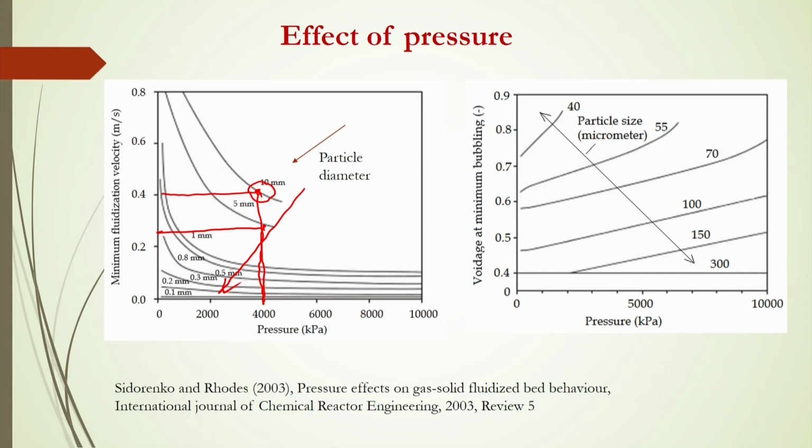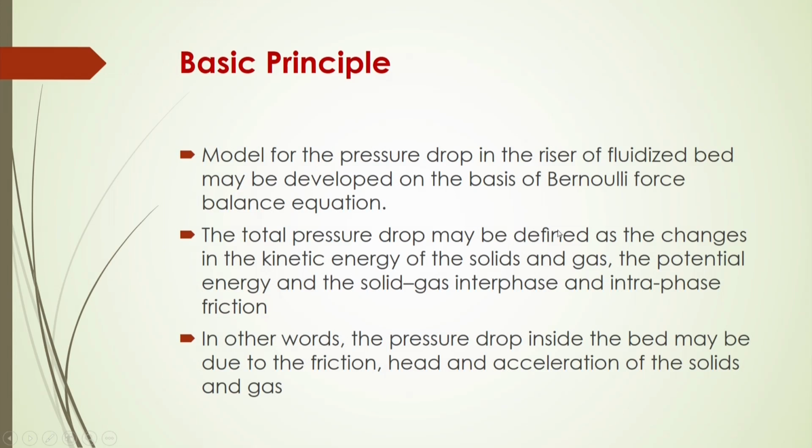So, the pressure drop at minimum fluidization or other conditions is required to be known, because for the design of a fluidized bed, we need to know in which flow regime it will be acting, and based on that, what the pressure drop from this operation should be.